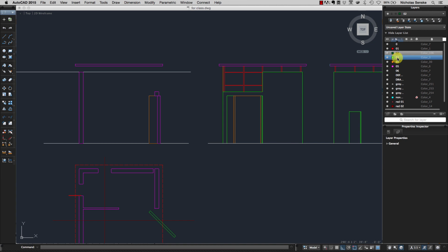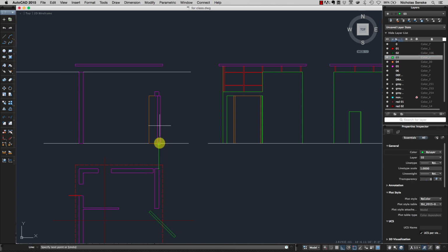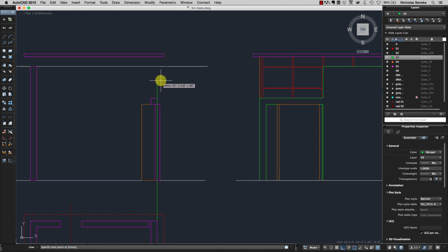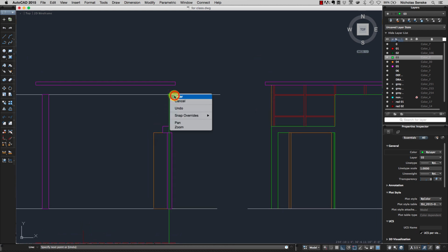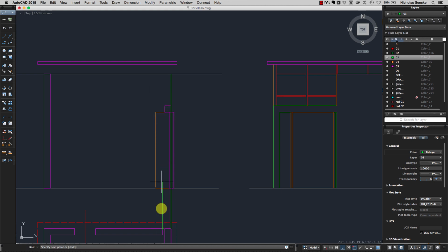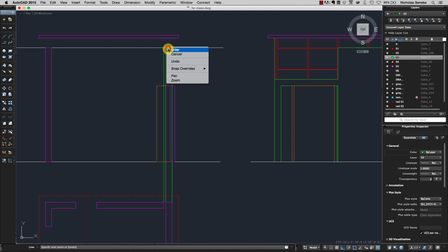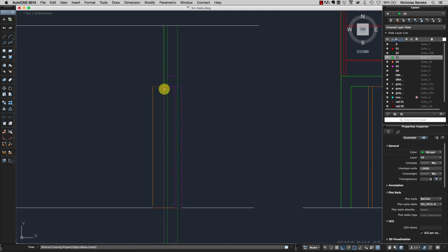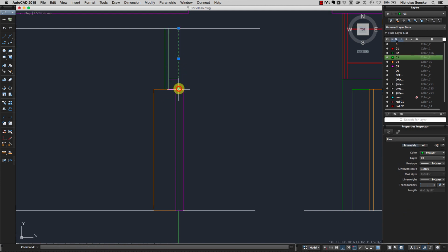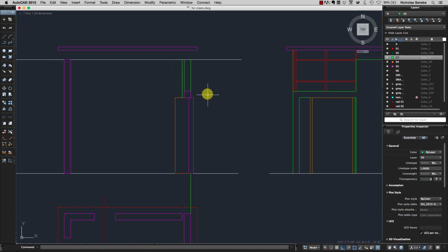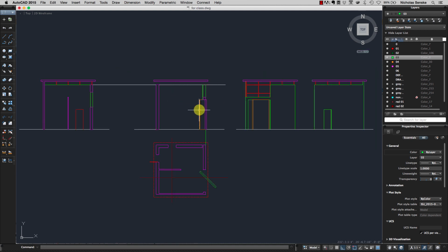It is actually, so there's an edge in the back, which is this wall, which does kind of keep going, and then there is actually a gap in that wall in the back, and I'm going to go ahead and trim these lines here. And again, I'm just going to kind of click and stretch these. It's a little bit easier than deleting them. Okay, so now I can read that as it drops back.